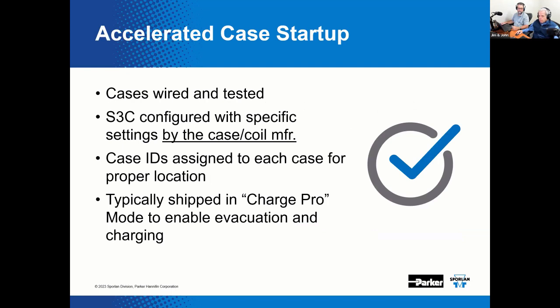Cool. Now, here's a list of the tasks that need to be completed by the refrigerated case manufacturer, the OEM. The cases will be wired and tested. The S3C control, or simply the control for short, will be configured with settings specific to each case, to each application. This includes, among other things we previously stated, the case identification or case ID. Presumably, no additional configuration effort on the part of the installing contractor would be required at the job site.